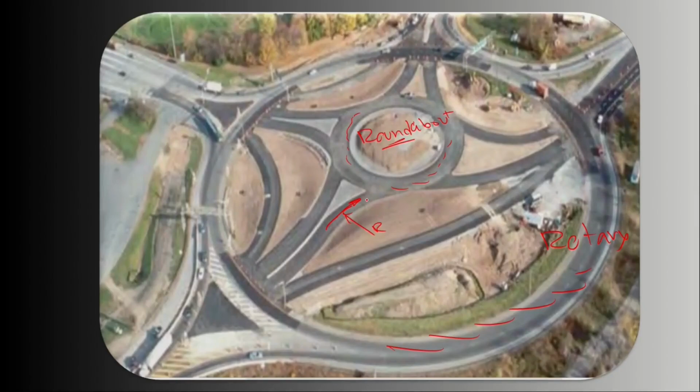Of course, as long as the volume can be handled by the roundabout. Also, generally, roundabouts have more capacity than stop-controlled intersections, since the entering traffic needs smaller gaps in between movements with a higher priority. We'll talk about this in more detail in the last section.